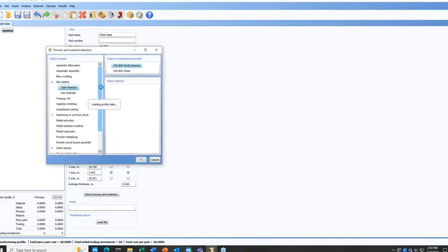So I'm going to choose this cold chamber die casting process again in this A356 material. Now, when the software starts, dynamic costing is turned off, and we're seeing all of the important cost drivers for every die casting. I'm going to turn dynamic costing on, and then we see a much smaller listing of responses.